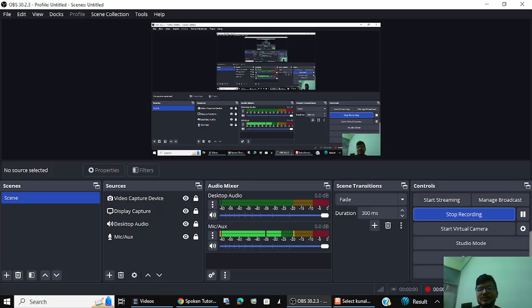Okay, so welcome to this next tutorial. In the previous tutorial, just as a summary, we created a very nice mesh of a pipe, and it was very simple to make. A couple of highlights include whether you add volume in your physical groups or not, otherwise you will face an error while importing the mesh in OpenFOAM. Second, you need to take care of the zero folder, because if the names mismatch, there is a high chance of a crash of paraFoam.